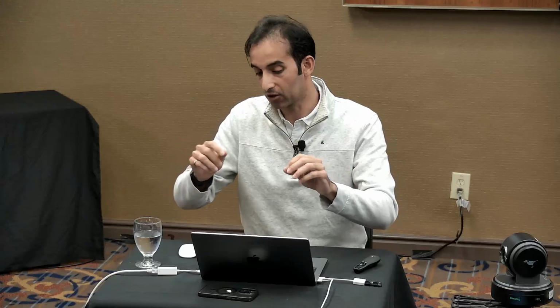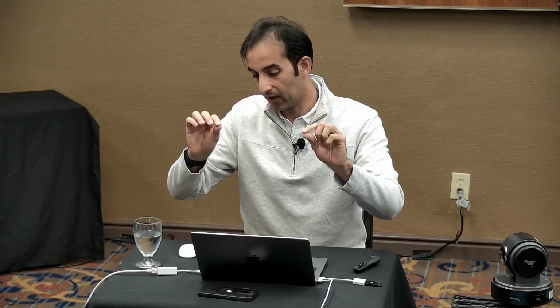How does it set the scale when you just have a PDF? You have to. I did it at the first step that said, this is my scale. Have you found out how accurate that is? I mean, a couple of pixels on this could be, yeah, over a 1 million square foot first floor of a hospital is going to be tens of thousands of square feet. You are able to change that, and then everything changes if you realize this is not correct. But also, if you have exact scale factors, then you're able to define that this is the scale factor there.